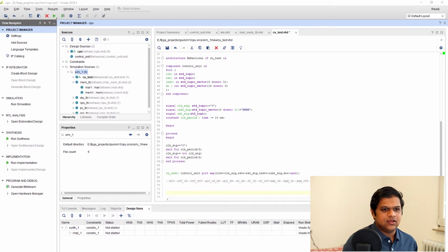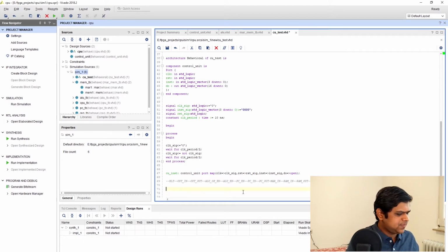So like we saw in our last video, the first two steps for all the instructions are the same. That is, fetch the instruction from memory and then increment our program counter. So in the first two steps we will do this. So let's write that. We will write it like this: data out is equal to, and we will assign our 17-bit value here.